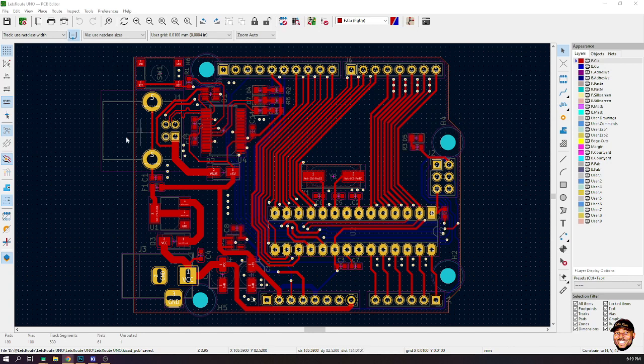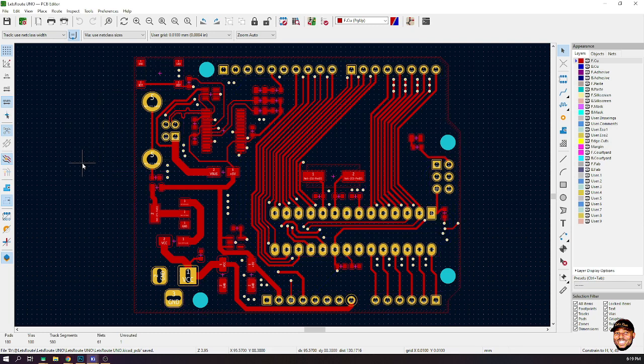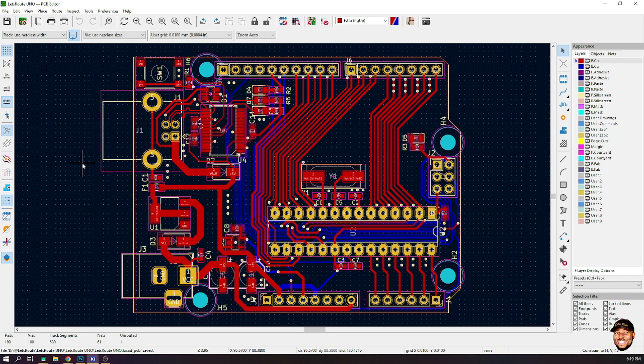Now, if you look at the board right now, you can see that the blue layer is now dim. It's called net highlighting, layer highlighting. So you can do that using the H key. As you press the H key, right now it's showing only one layer at a time. If you want to show all layers at a time, you just have to keep pressing the H key and it will toggle through it. When you get to any point that you want, you keep it.